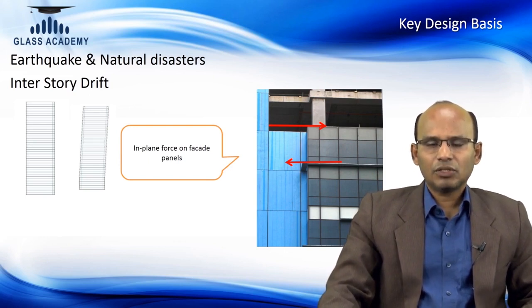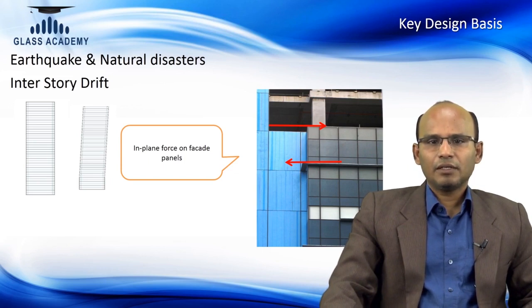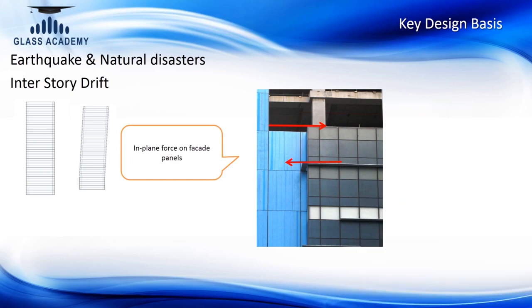As structural engineers should be aware, the facade system or its material is a very strong element in supporting out-of-plane loads like a wind load acting on a plane. It may be weaker in its own plane, on this minor axis loading. So the building sway may impose minor axis loading, which needs to be checked during the design.